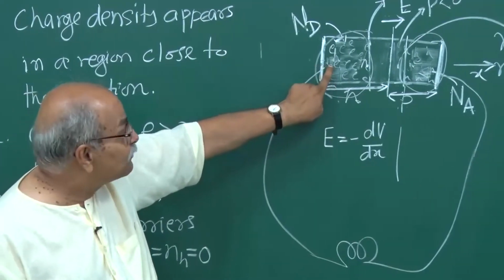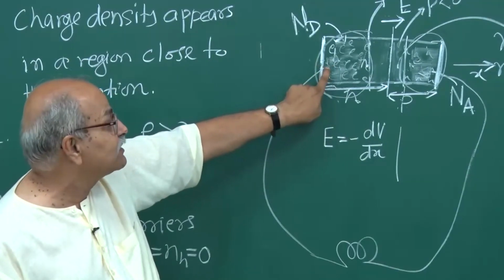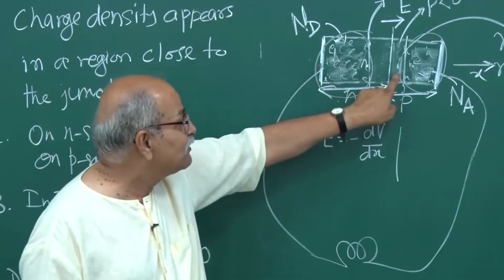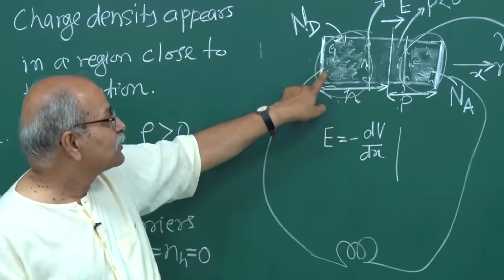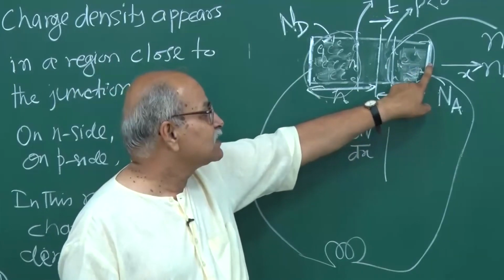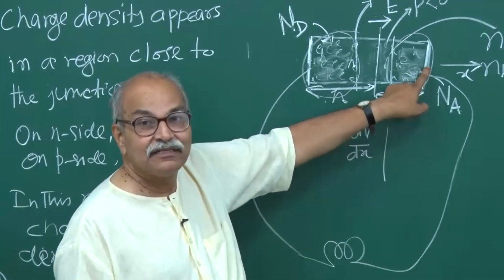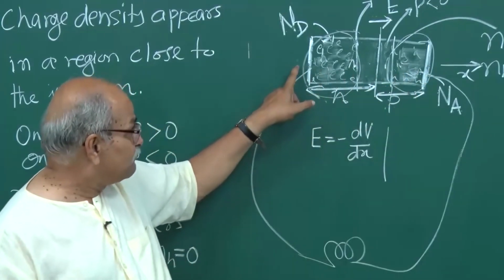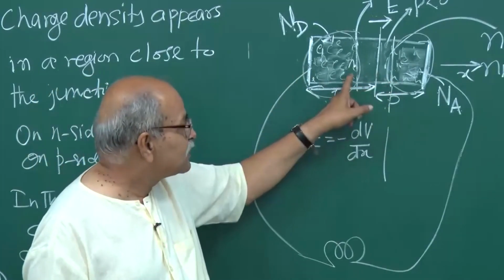You have the doped semiconductor here, and then you have the metal here. Once you go from a semiconductor to a metal, there is a junction out here. So you do have a potential difference here also. As you have a potential difference across this junction, you also have a potential difference across this junction, and similarly across this junction. Semiconductor to metal, there will be a contact potential difference, here there will be a contact potential difference, and here also there is a potential difference.